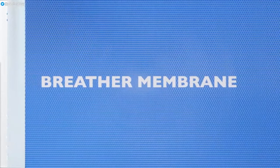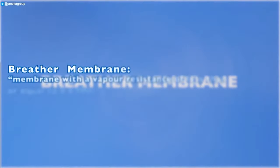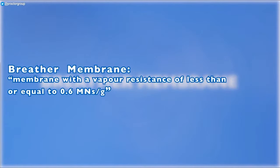Breather membrane: membrane with a vapour resistance of less than or equal to 0.6 meganewton-seconds per gram. It's probably more accurate to refer to breather membranes as being vapour permeable rather than breathable, as this helps avoid any confusion associated with the air and vapour permeability of the material. The BS 5250 definition currently concerns only the passage of vapour, so membranes can be either airtight or air open.